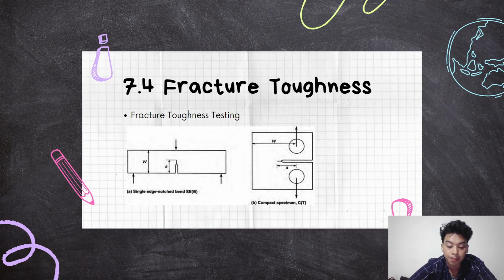Fracture toughness. Plastic deformation in crystalline material occurs by the process of shear. See Chapter 3, Mechanical Properties and Strengthening Mechanisms, in this book. The actual measured shear strengths of real engineering materials are often several orders of magnitude lower than the theoretical shear strength of a perfect defect-free structure.